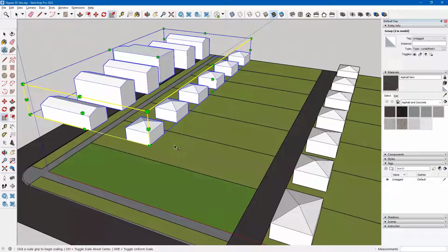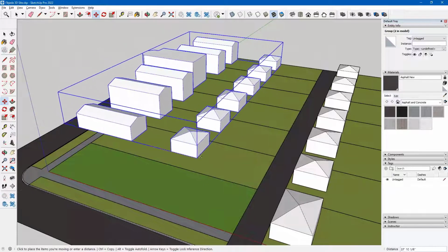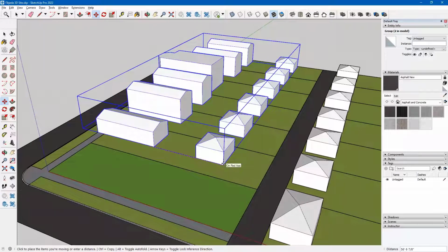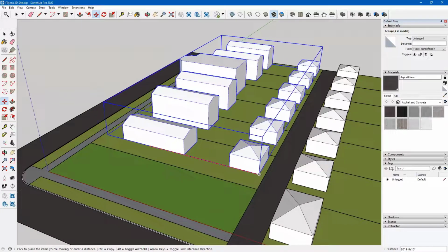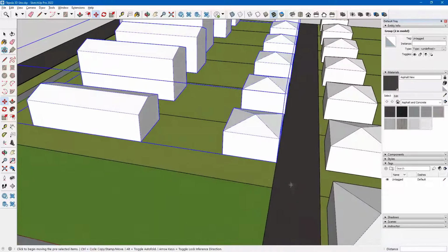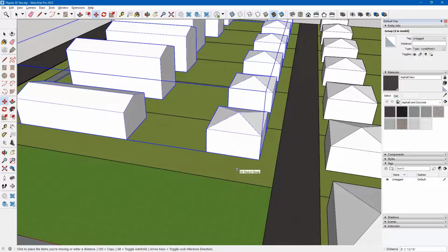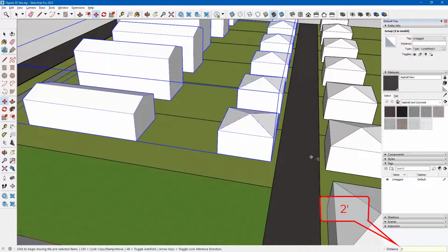I'm simply going to type M, take it from this origin point over here, make sure I lock into red by using my right arrow key, tap that. And I'd like to lock it in so that it aligns to this intersect here, this point. And then from there, I know I can move it again. And this time I'll pick right here outside. And I'd like to bring it over 2 feet, 2 feet because that was the same distance I had on the opposite side.